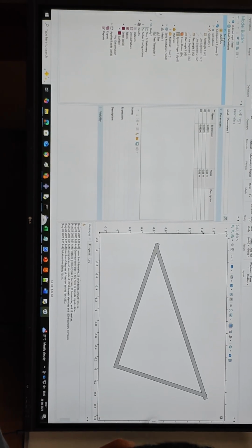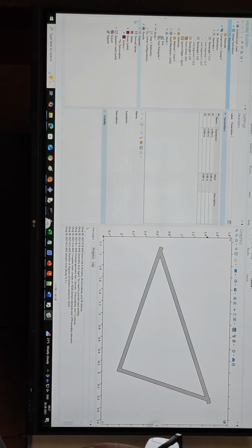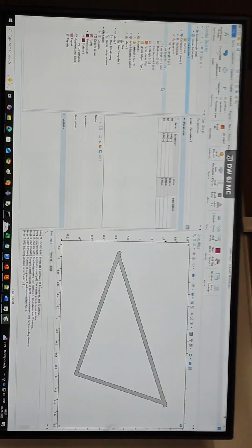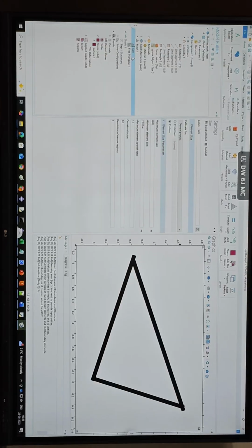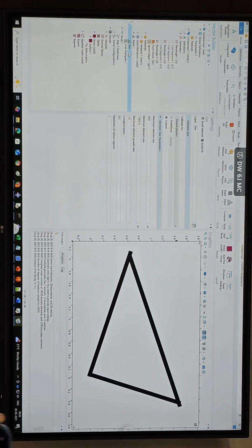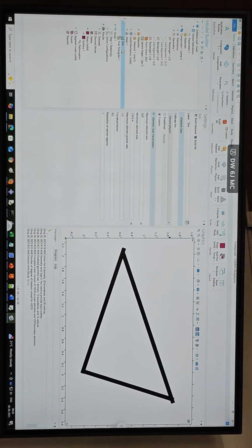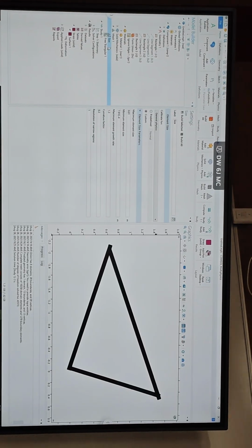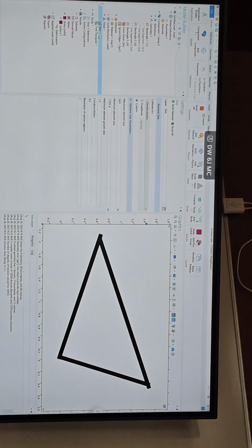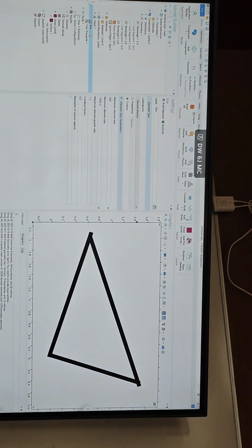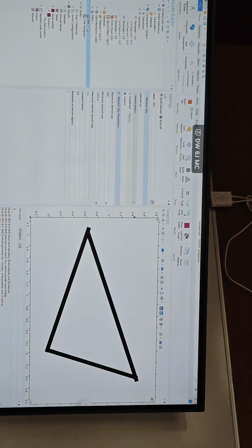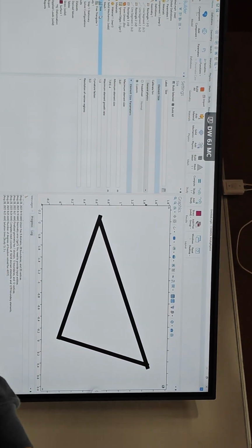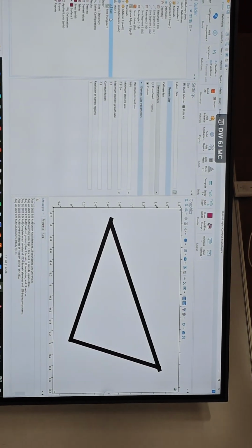Okay. Let's hold the other questions. Let me just finish this. Now, once you try this, you can always go back here and just try a mesh convergence. I took a very fine mesh, but if you start with a coarse mesh, you can proceed with a mesh convergence. There are other ways to play around with this. Make sure that your load is as axial on all the elements as I told you, instead of having it highly transverse. So you reduce the bending dominance in some sense. You're putting the component of load as much along the axis of the beams as possible. If you have a complicated structure, all the best again, but this is the way you at least initially approach it.